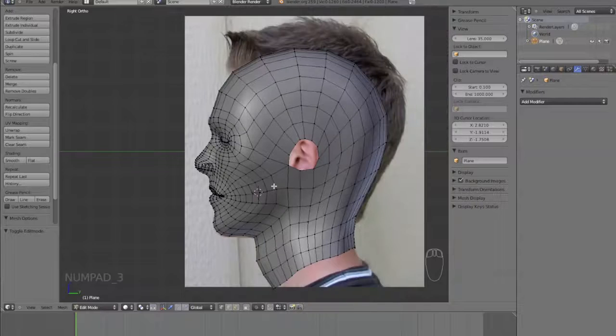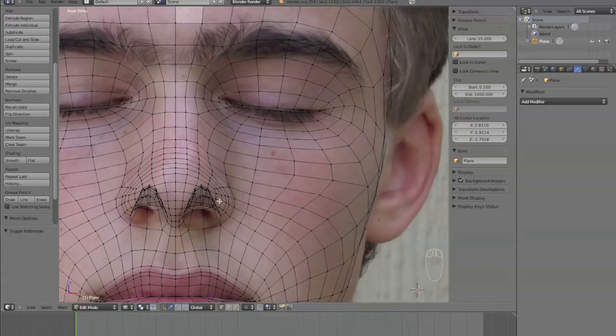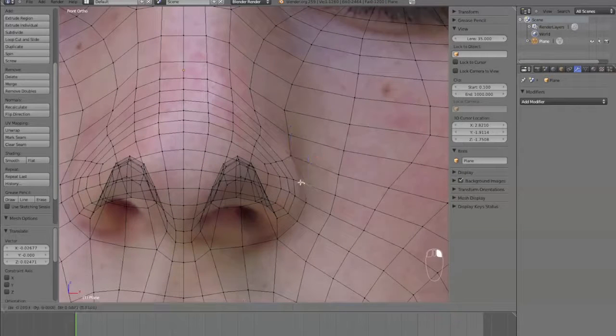Pressing Option B and selecting part of the mesh will restrict the 3D viewport's viewing area so that it will only display that portion of the mesh. It will now be a lot easier to tweak the vertices on the mesh because the verts from the back of the head will not be obstructing our view.